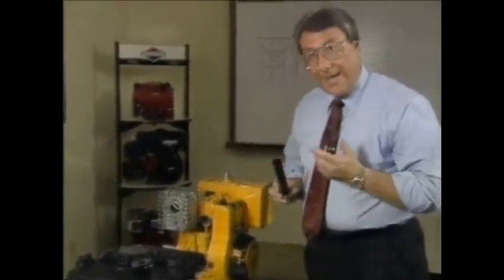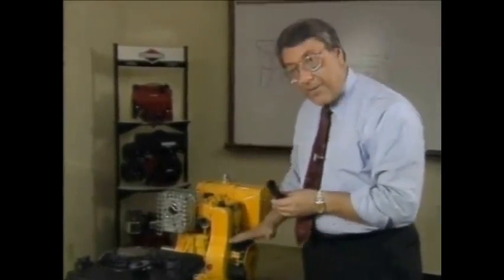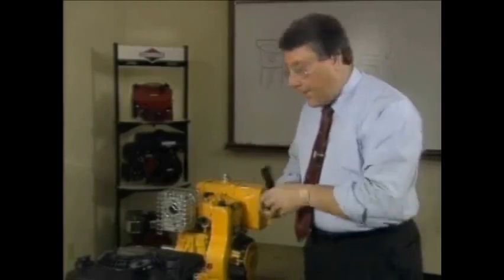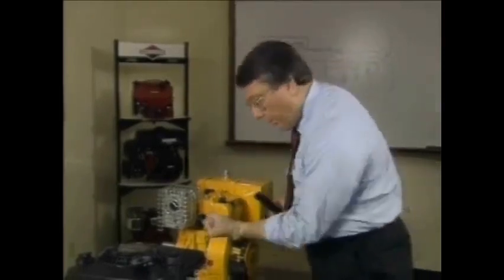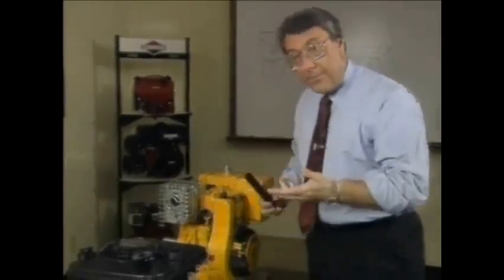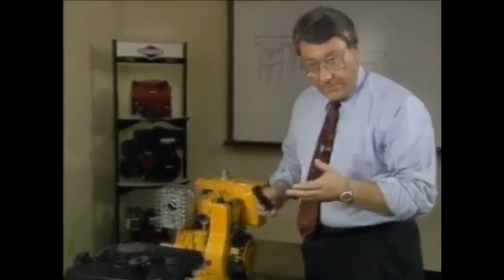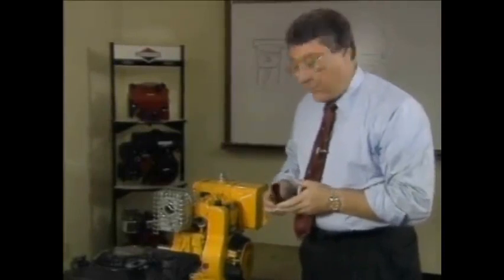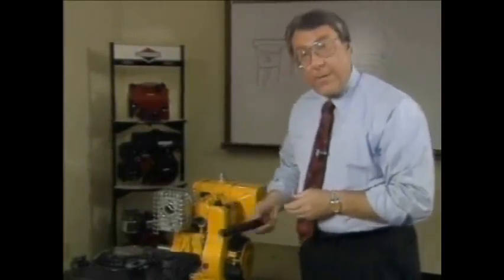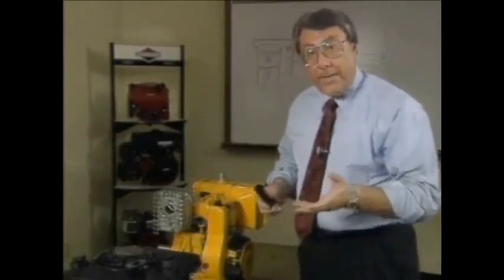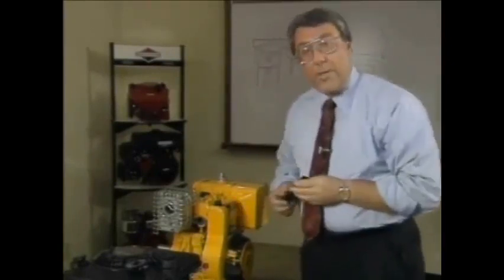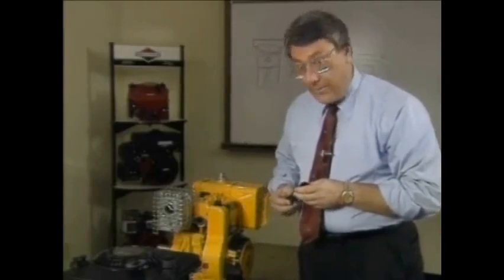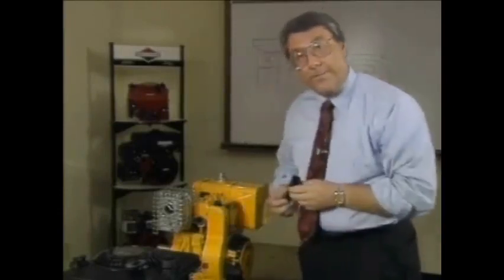Keep in mind that as the piston moves down in the cylinder, a void or vacuum is created in the cylinder, and the air surrounding the engine is pulled into the cylinder in an attempt to fill the void. That is, providing all things affecting engine compression are functioning properly, such as valves, gaskets, and rings. That takes care of getting air into the combustion chamber, but how does the carburetor get the atomized or vaporized fuel into the combustion chamber?